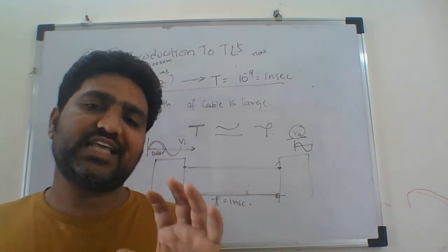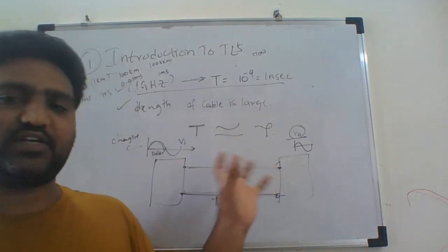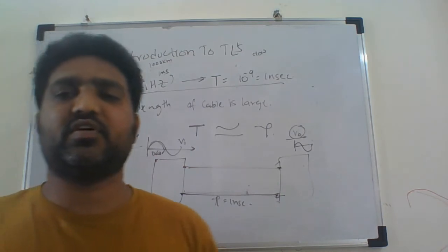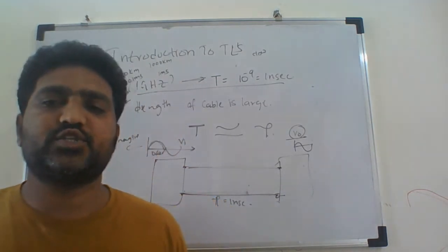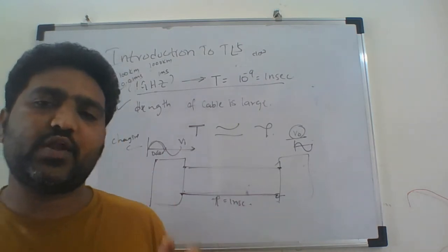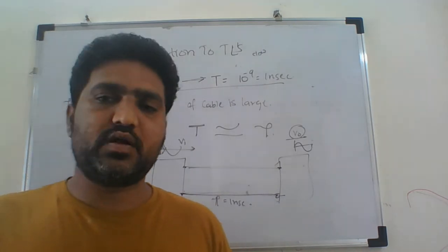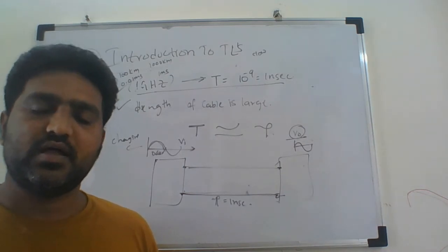This overall effect of the cable impacting the analysis of the signals is what we call the transit time effect. Because of this transit time effect we cannot do the traditional analysis; we cannot neglect the wires or the cables.